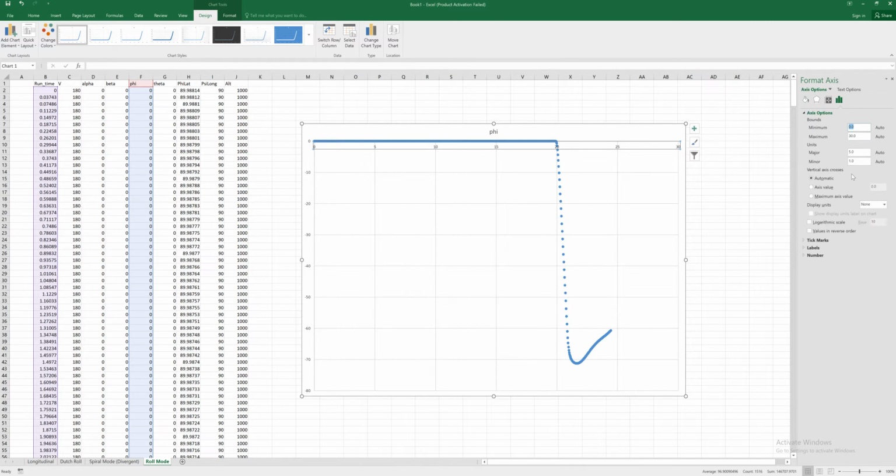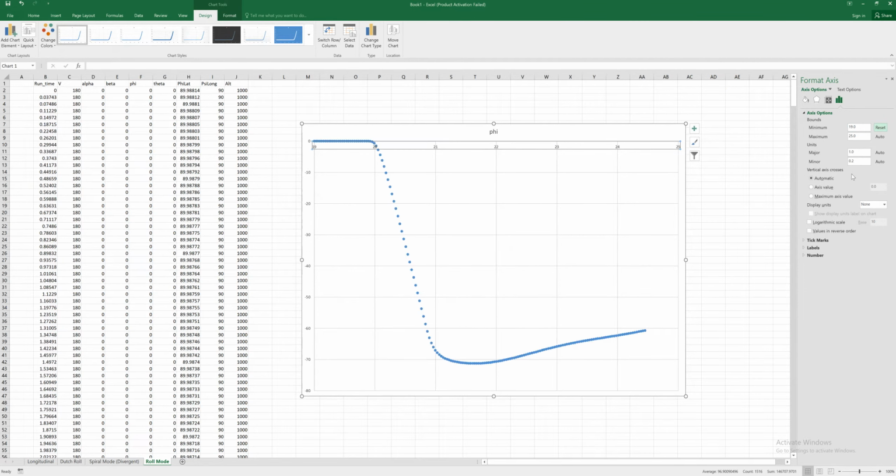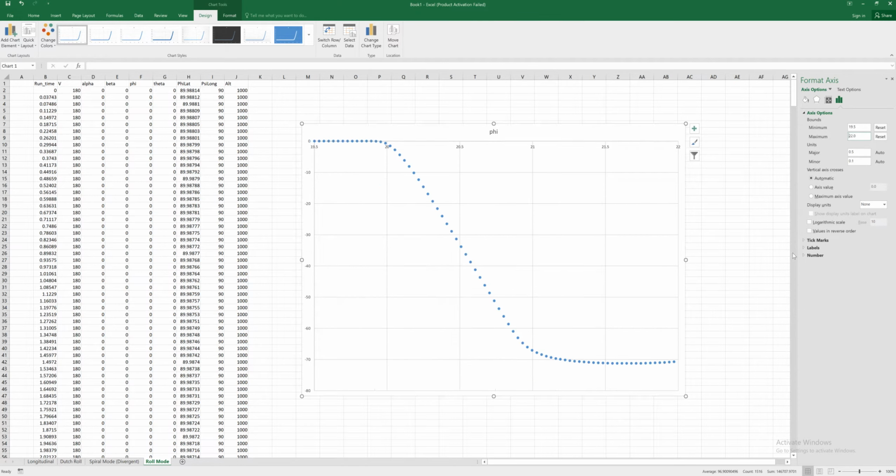So let's see, we started that at about 19 seconds. And let's actually go 19.5 and really zoom in on this. And then we're actually going to come up here to about 22. That should do it. Okay, so what we're trying to measure here is how rapidly do we approach a steady change in roll rate. So that would be when this line hits a constant slope. So we're trying to look at how quickly do we change from 0 to something that has constant slope.